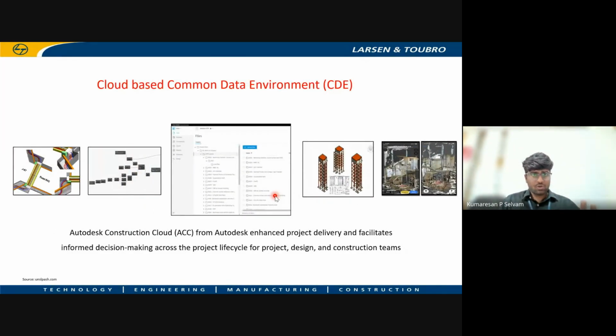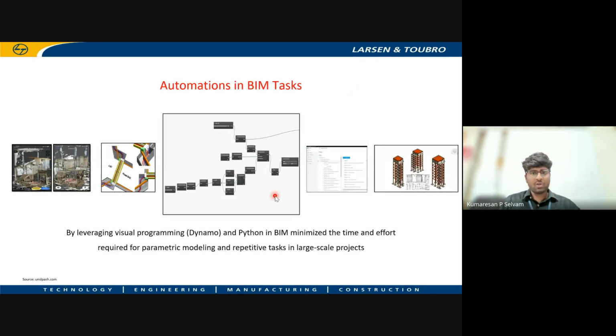Then, as I told, common data environment and automations in BIM tasks. We are using the visual programming tool Dynamo and Python for automating more repetitive tasks, like deletion of unused views. In a BIM model, if you keep increasing the views, the size of the Revit file will increase.